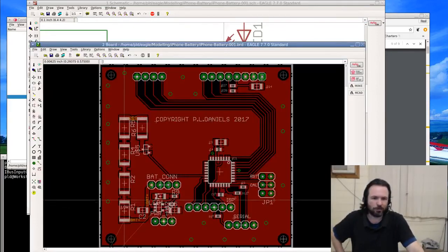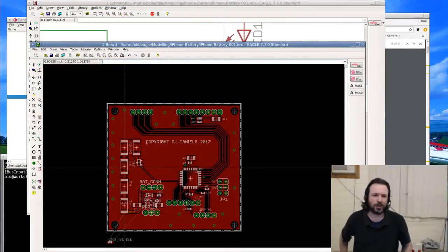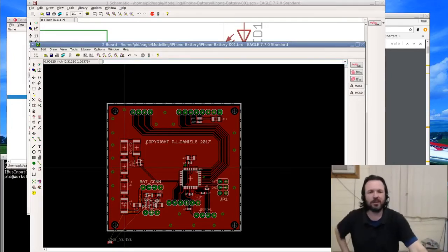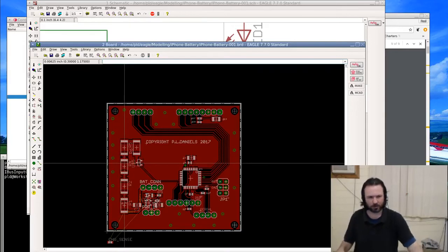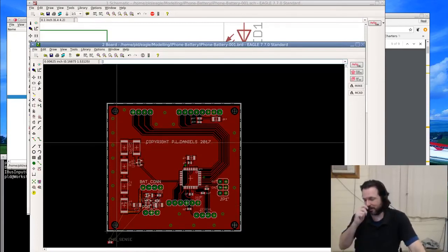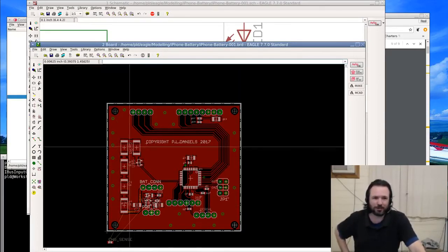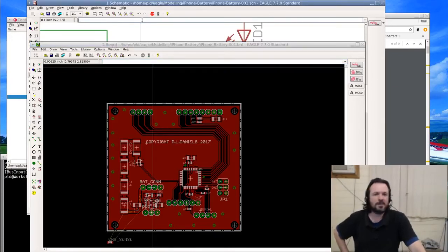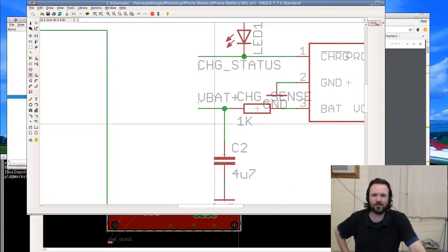Philip, the reason why I've got 4 in series there is just simply for cheapness, and it gives me some wiggle room if I want to change things around a little bit. They cost me like $0.01 each, the 2512 1 watt capable resistors. And it does give me the advantage that I can tap into just one of them here and give myself a current sense. And it's actually 5 resistors, but yeah.